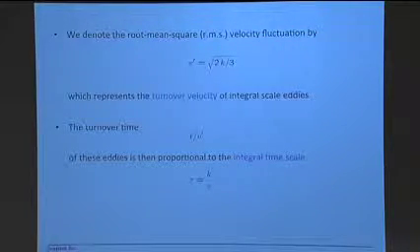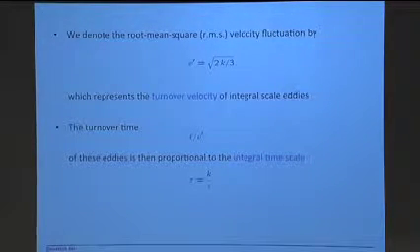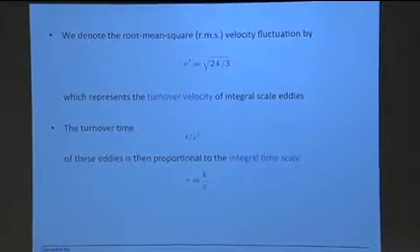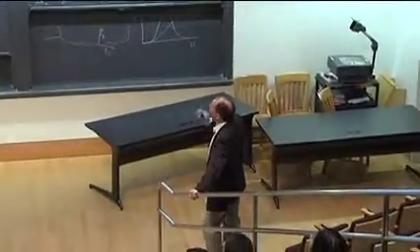We call epsilon the dissipation rate, but it's also the energy transfer rate in this inertial subrange. So this energy transfer rate is very important, and so it can also be used here to define a time scale of the large scales of the turbulence by k divided by epsilon.